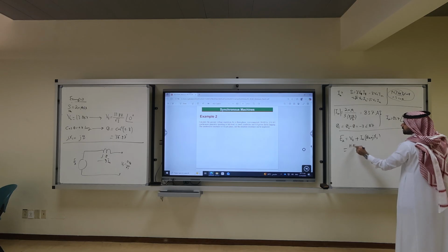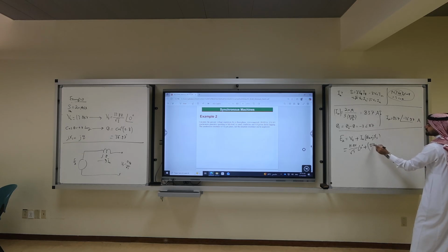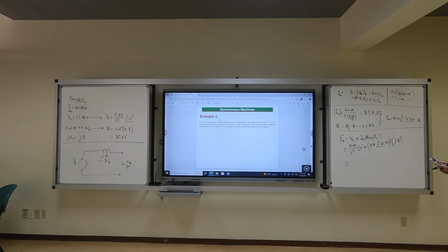It's 13.8 kilo over square root of 3 angle 0 plus what is IA? 837 angle minus 36.87 times j8. Calculators: 13.8 kilo over square root of 3 angle 0 plus 837 angle minus 36.87 times j8.